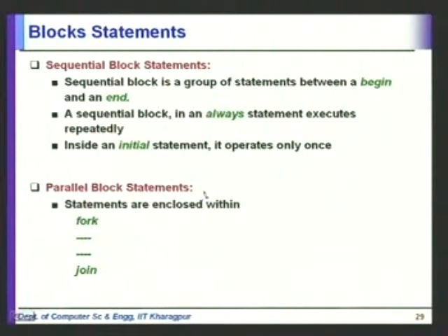You can also have parallel block statements, which can be described by enclosing them within a fork and join. Whatever statements are between fork and join, you can think of them as executing in parallel. Okay. This is in behavioral Verilog.